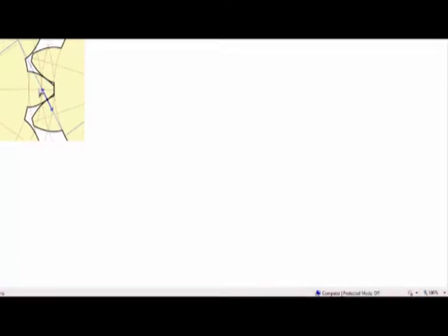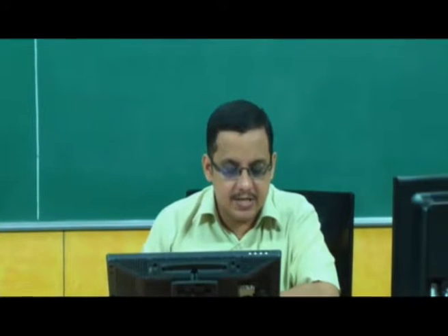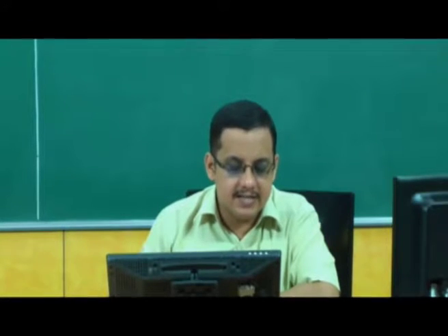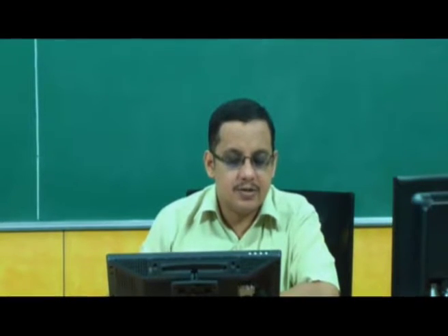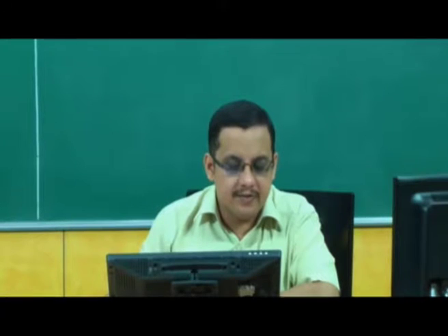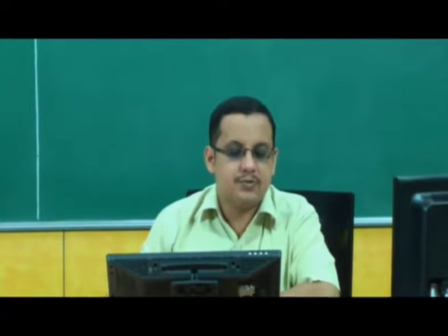of engagement. So this animation exactly shows the course of engagement and disengagement between one tooth pair, and if you carefully observe, you can find that the blue dotted line always turns out to be the common normal. Then the pitch point can readily be identified as the point of tangency between these two red dotted circles. These are the pitch circles. So this is the pitch point, and you can observe that the blue line always passes through this point.